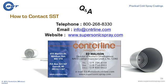So long as those properties are in the cold spray coating, I see no reason why you couldn't apply another thermal spray coating, another cold spray coating, or an organic coating, a polyurethane, an epoxy, an alkyd, medium oil alkyd coating. So again, work with us on the specifics. But my answer to that question is, yes, it appears you could accomplish a 2-coating system starting with cold spray and finishing off with a plasma spray coating.